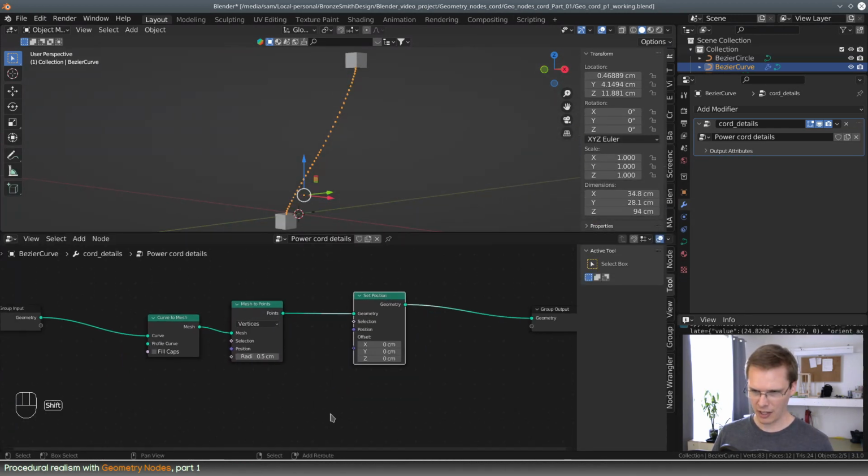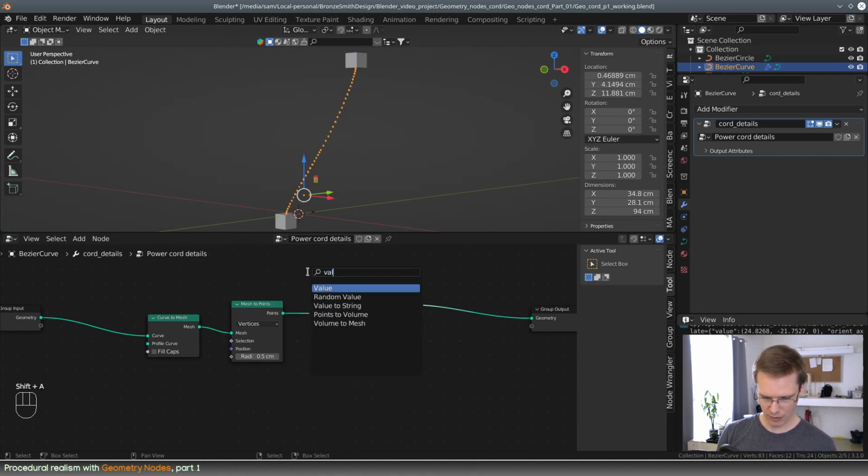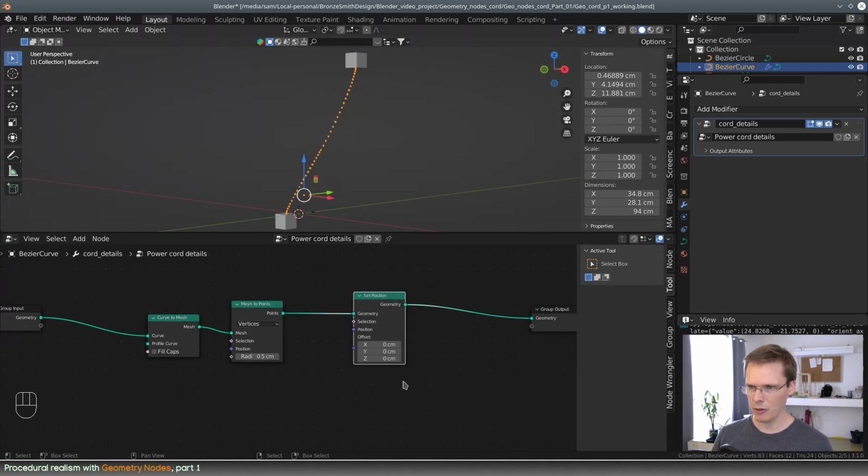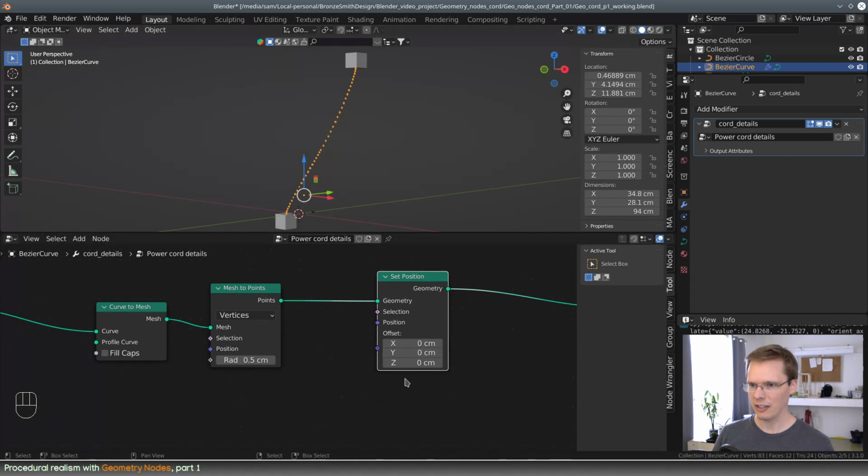So we're going to then take a value. No, first of all, we're going to demonstrate. Okay, so offset. You can set position for points. The set position, what it does is it sets the absolute position. So this is vector based. So if you want to set it to 3 numbers, like positive 2 in z, negative x, and negative y, or something like that, you set the absolute positions in global coordinates.